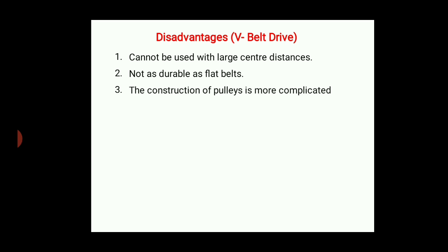The construction of the pulleys is more complicated, as they have to be made to accommodate the corresponding size of the V belt, and the cross section of the V belt should match the cross section of the pulley groove. That's why its construction is complicated as well as costly.